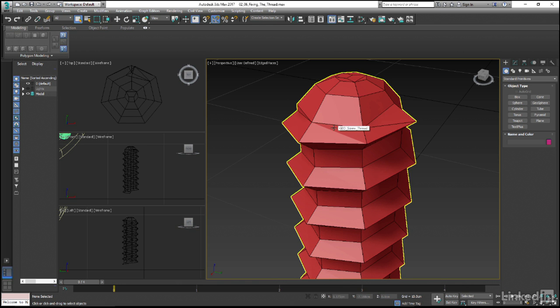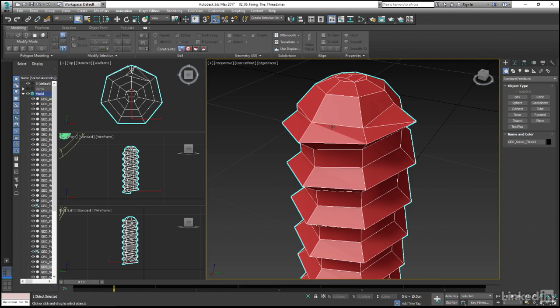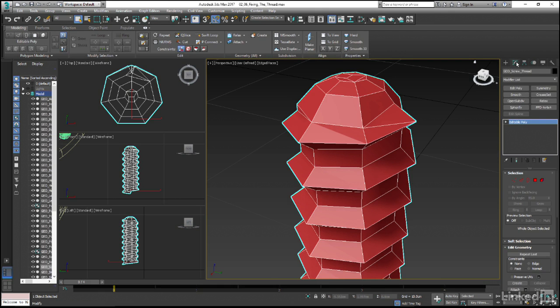Doing this is actually quite simple, in that all we need to do is select the Cut tool from the Edit panel on the Ribbon UI, and from the top vertex sitting at the end of our thread here, making certain that our cursor does change and so indicate that we are over a vertex, simply click to start a cut operation, taking that all the way across to where the spiral actually starts again, bypassing the flattened edge altogether.